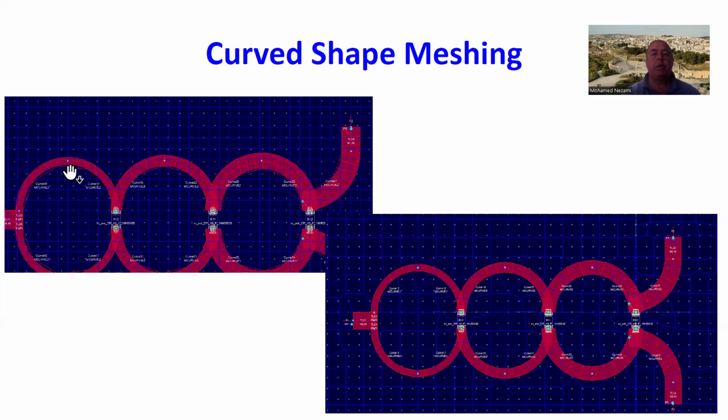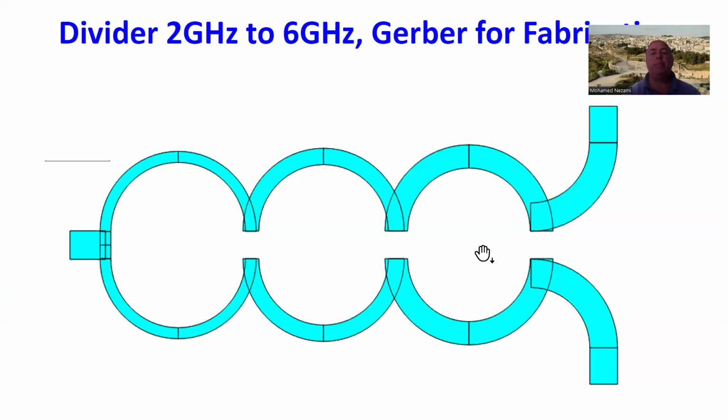As you can see here, the meshing transformed the curved lines into a set of straight lines, and it interpolated the actual physical dimensions, and you can get inaccurate results. Now, after you do the settings correctly, you can see that the meshing is now following the curved lines, and you're not skipping any copper. You're meshing the whole copper, okay?